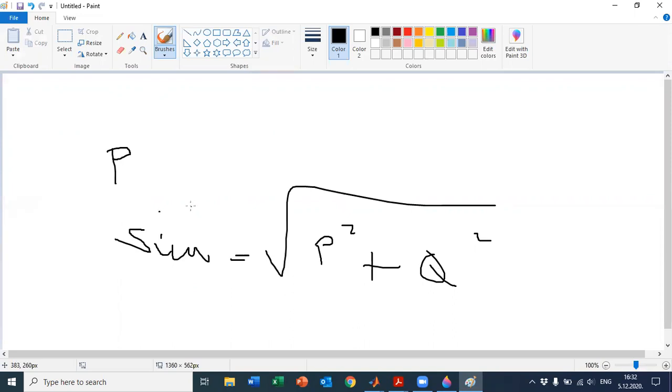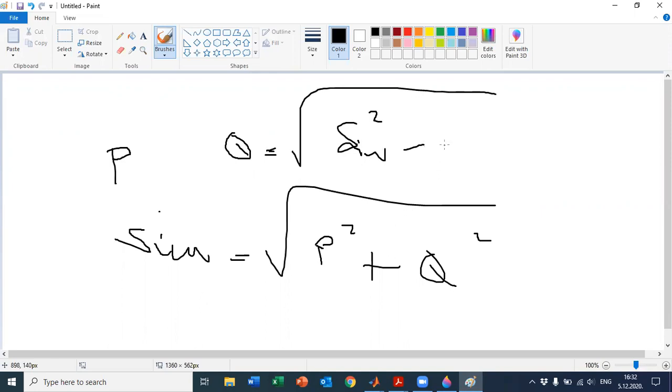And basically, if the generation of the PVs is equal to P, then the maximum reactive power which our generator can give is equal to Q, the square root of S inverter, which is the nominal inverter power squared, subtracted by P squared. So the reactive power which our PV and inverter can provide is dependent on the power given by the PVs.